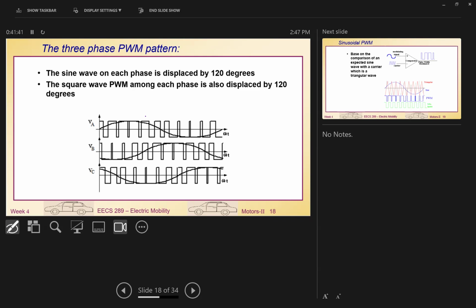So you have one wire here, another wire there, many turns, isolated by the enamel. Between them there is some small parasitic capacitance, just like between two insulated cables. Although small, maybe picofarads, it is still something.